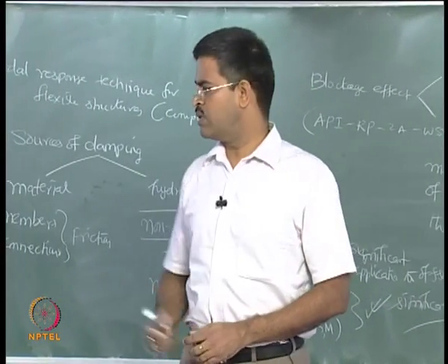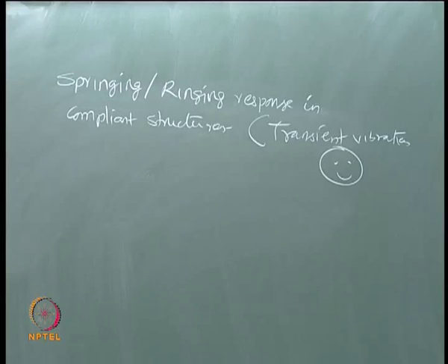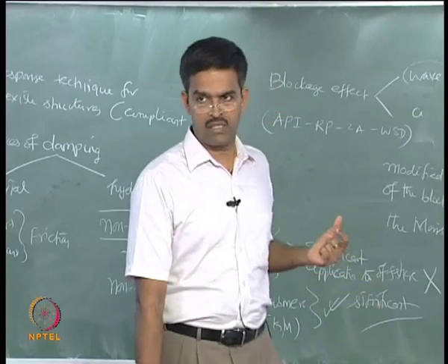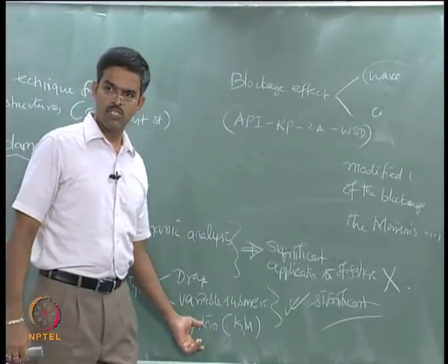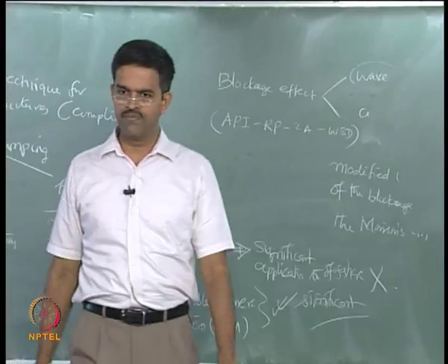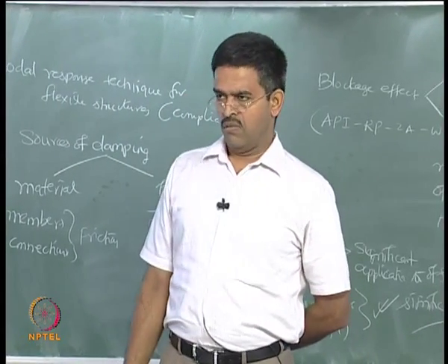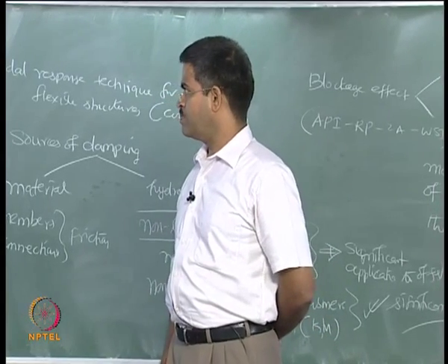I will show you in one of the case studies we will take up in the next lectures how ringing or springing response can become phenomenally high in compliant structures, because they will be addressed only to the system non-linearity coming from the geometry, not for fixed structures. People have reported this kind of studies in the literature, which we will show and discuss in the subsequent lectures in this module.